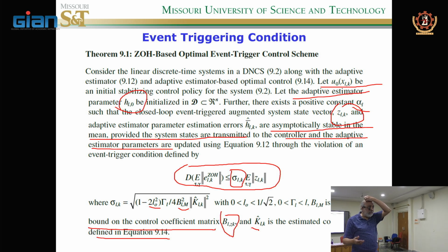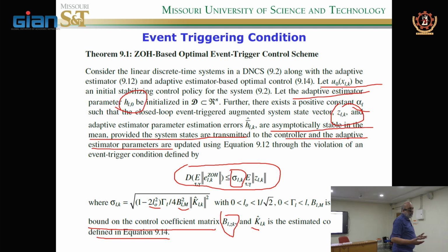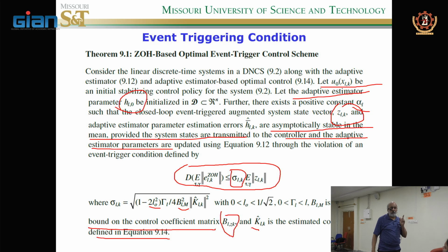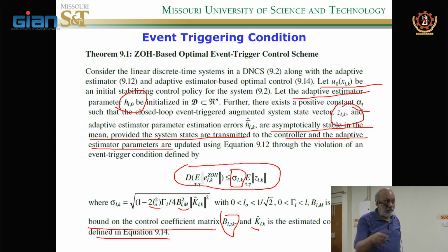So imagine you have a subsystem in a power system. There will be states. In that region there will be 2 generators, and in a different region you might have 4 generators, so you are controlling the generation also. There are states, and that information, if you are transmitting through the network, could have potential congestion. It depends on how many sub areas you have, and it all depends on the bandwidth of that network. So power systems use a wide area network. Refineries also use that.